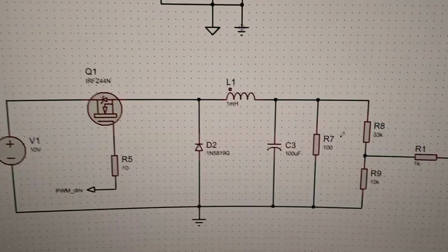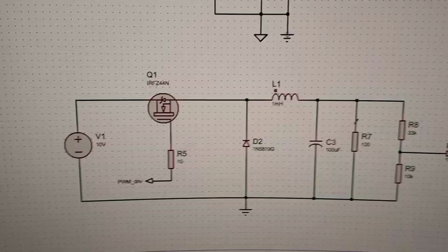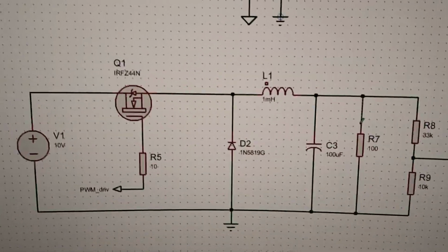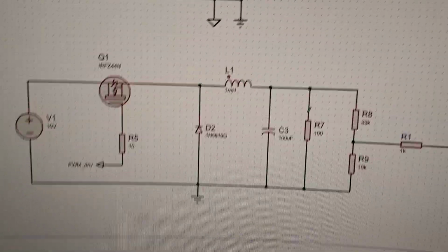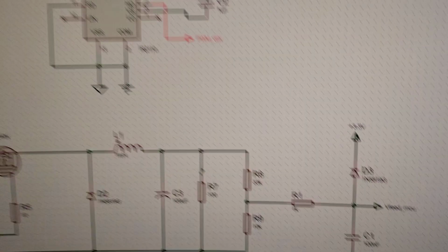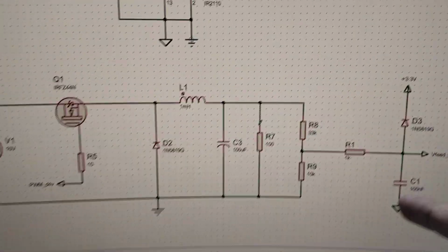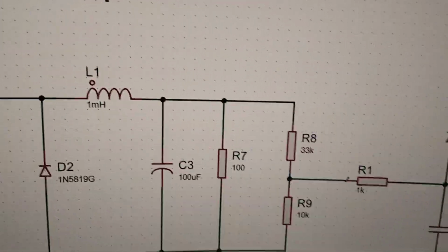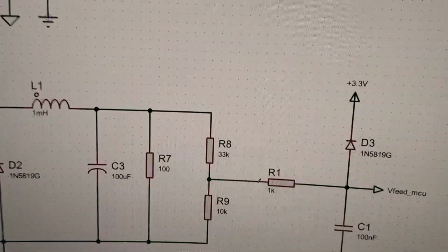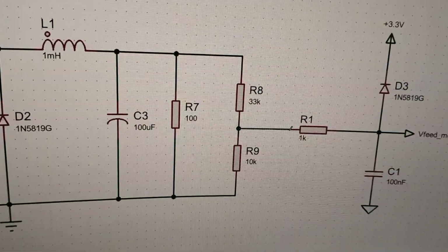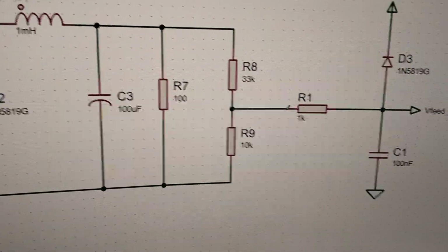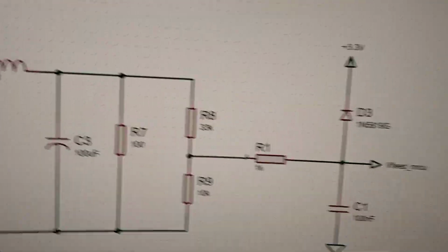This is a buck converter, so as such you won't get a voltage greater than your input voltage. That's literally the point. It's a buck converter, it steps down voltage. But later if we do the boost, this will play a much more important role, because let's say something happens. Of course nothing should happen in normal cases, but let's say something happens and suddenly the voltage across this shoots up to let's say 8, 9 or 10 volts or even higher.